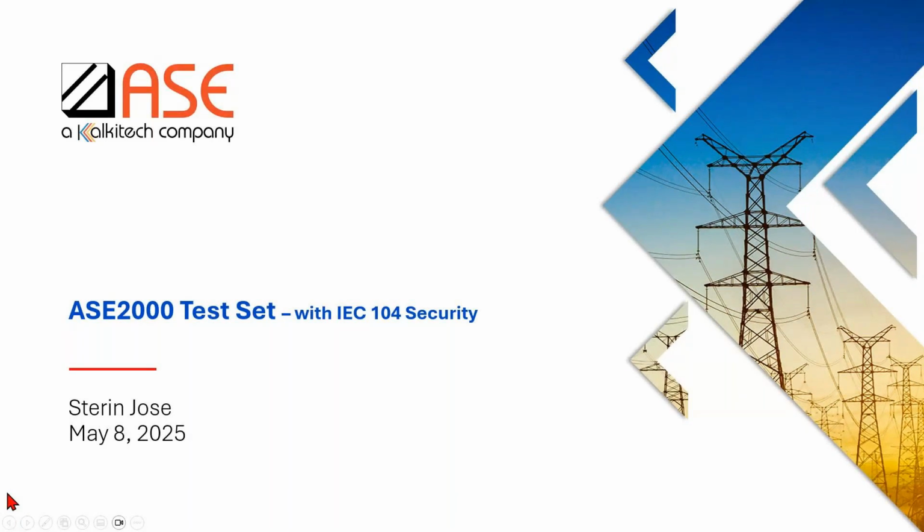So today we are going to discuss how to test IEC104 Secure Authentication features. This webinar will cover IEC104 Secure Authentication capabilities introduced in our product ASE200 Test Set, the latest version being 2.35. Test Set will support both TLS 1.2 and 1.3 for transport profile security. We will also be covering some of the other fixes and improvements in this particular version, and fine-tuning terminal server versus COM versus TCP selection, etc. for the DNP3 protocol.